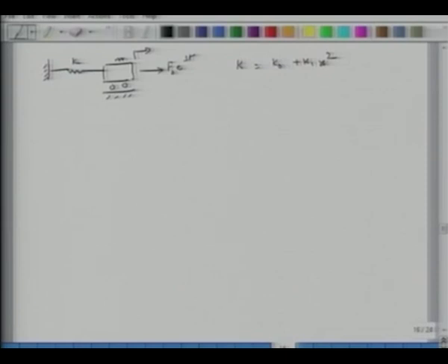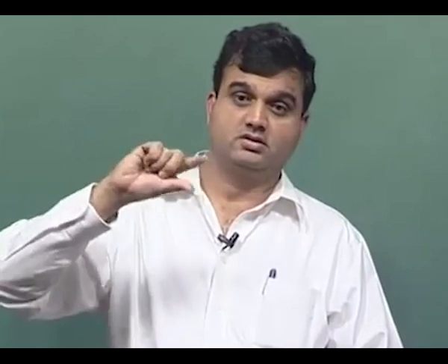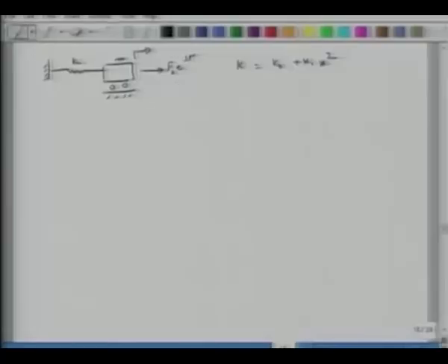This very simple model has direct application in transducers. So you have force which is being generated by which part of the loudspeaker? The voice coil. That is generating force on the membrane. So that is your F naught e^(st). Then there is the moving mass of the loudspeaker, which is M. And then there is stiffness. I have eliminated damping here for simplicity purposes.